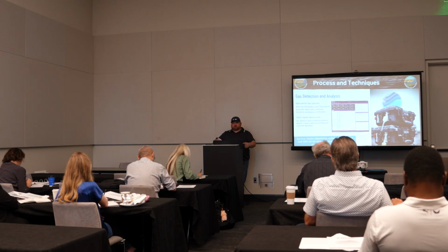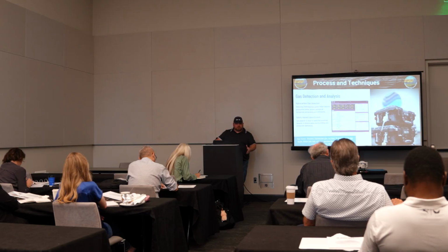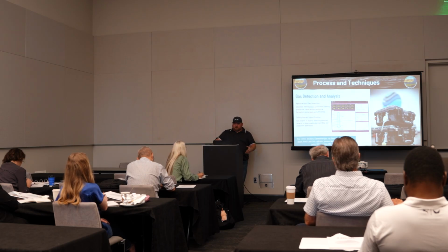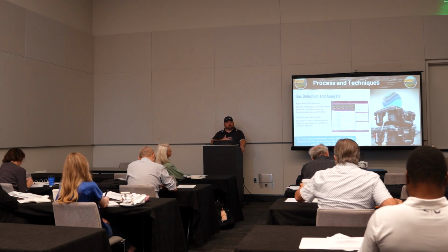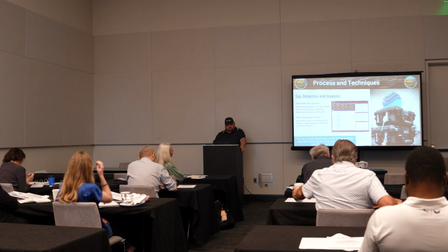Being able to analyze that specific foot from a mudlogger standpoint helps the client tremendously by saying, okay, this is here, I need to look at this more. In turn, they can use a wireline log, seismic, and all that to look at it more in depth. But it starts with us as mudloggers on that hydrocarbon analysis.